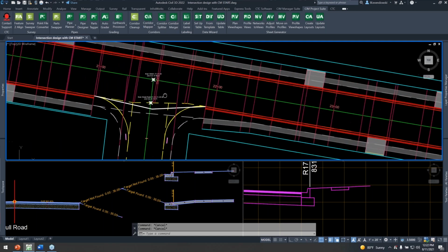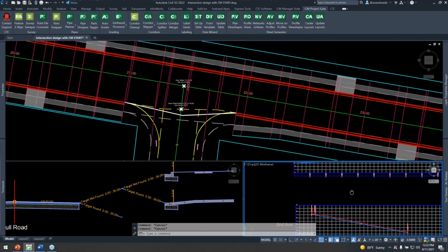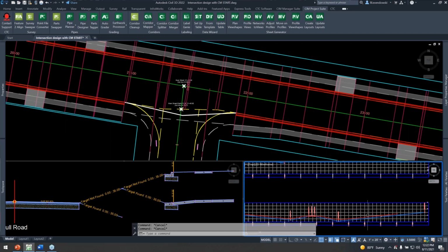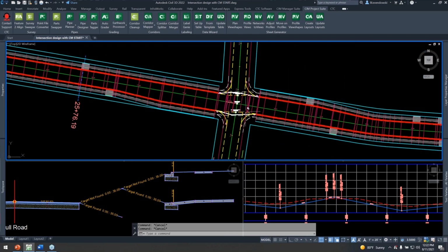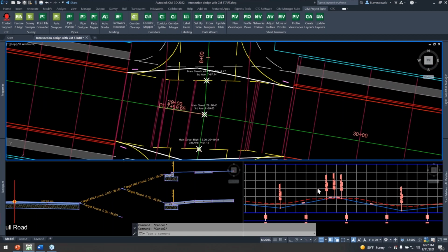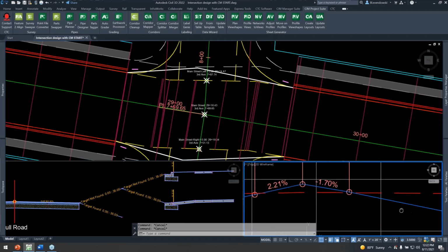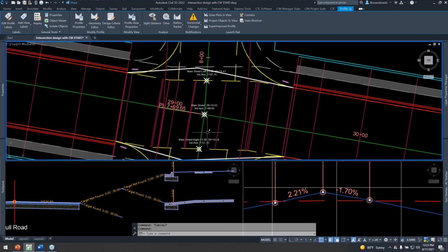Now, when it comes to the crossing alignments and profiles at intersections, there's another little trick I'd like to recommend here. Let's take a look at our crossing alignment and profile at this intersection. I've got alignment crossing here, a four-way intersection. What I use to link the profiles together is the native intersection tool. If I look at the profile, this is the north-south road here. You'll see I've got locks on here. These PVIs are locked to the cross slope of the through road.